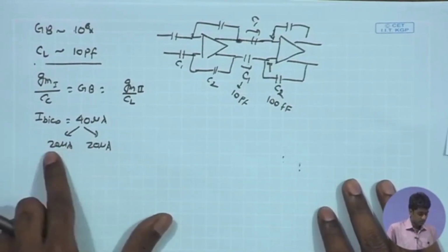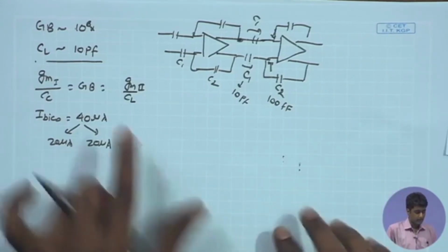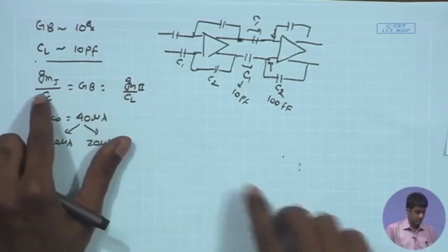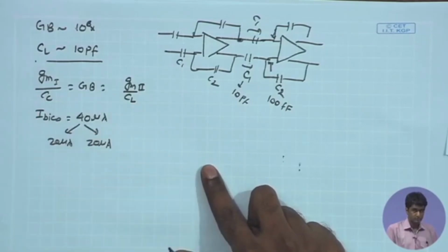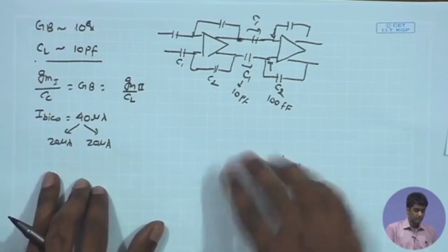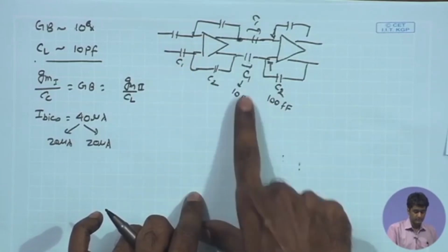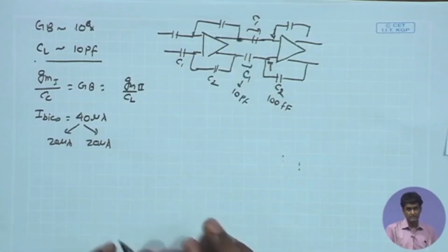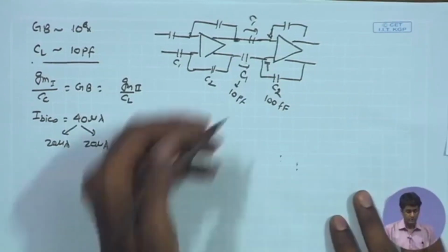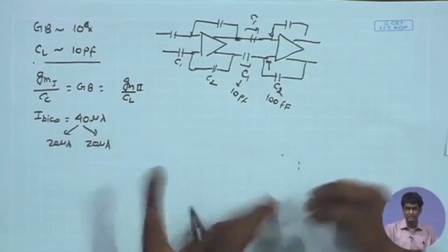So, I have the bias current requirement coming over here, and then I have the overall CC and CL ratio, which is supposed to be determined considering the overall area. If you remember the capacitance C1, it is the largest capacitance over here as compared to C2. This value is much larger, and as a result it is going to be the most area consuming part of the front end amplifier. Whenever you go for capacitive feedback or even resistive feedback, the larger passive component takes the maximum amount of area.